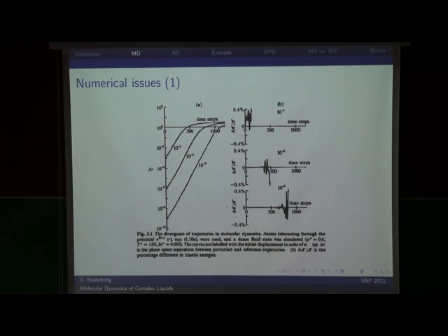And we can also look at the divergence of energy and see it's roughly constant, and then suddenly it's going to explode. And the smaller a time step you take, the longer the energy stays conserved, but ultimately it explodes. And this is a problem, because it means that you can only run simulations for a short while until we don't have energy conservation anymore. And this is of course because we pick up numerical errors in this integration scheme. And regardless of how short a time step you take, sooner or later we are going to run into this problem.